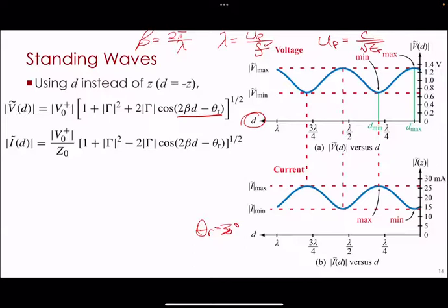So now you're designing a circuit for the iPhone 17 or something, and it needs to work at a bunch of bands, but the one that you're interested in is 1 gigahertz. Okay, so F is 1 gigahertz. That tells you the denominator of lambda. The numerator UP depends on epsilon R. So I tell you, you're designing it on a printed circuit board. It's got a pretty high epsilon R. The value is 9. Okay, so what's UP?